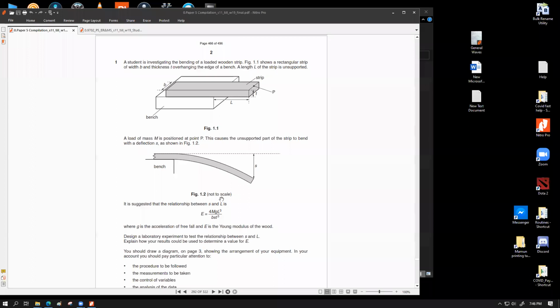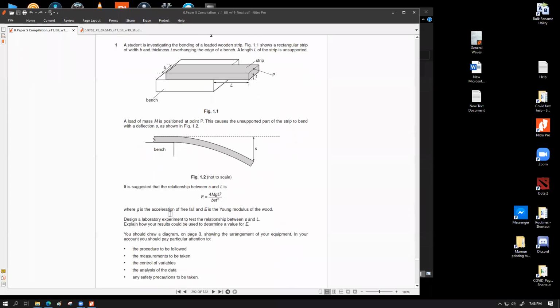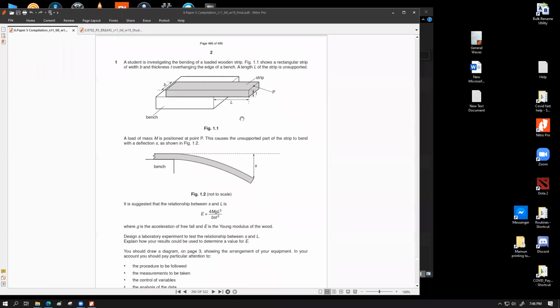B and A, what is B? Do they say anything about the B? Acha, yeah, B is the thickness of the wood. So we're going to use a single piece of wood, or we can use identical pieces of wood, so that if there is any possibility of plastic deformation, we can continue further down the experiment. What I mean is that, let's say you take three sets of readings with multiple repetition, and then the wooden plank bulges away. So you have to use a new piece of wood. So we should have access to multiple pieces of wood.